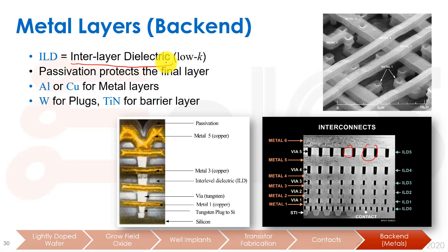In fact, it used to be silicon dioxide, since we don't want all kinds of coupling capacitances in general between top and bottom, between the contacts, or internally in these metals between their pieces, like between this guy and this guy. What we do is we actually change the material here, so instead of silicon dioxide, nowadays it's a low-K material. We'll discuss that in a later lecture.